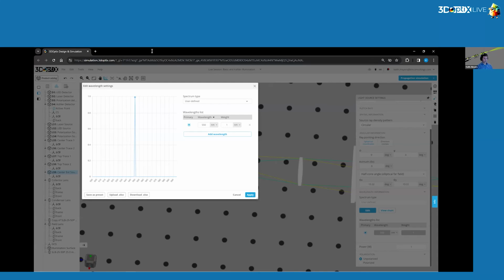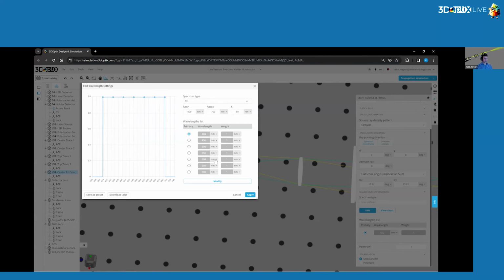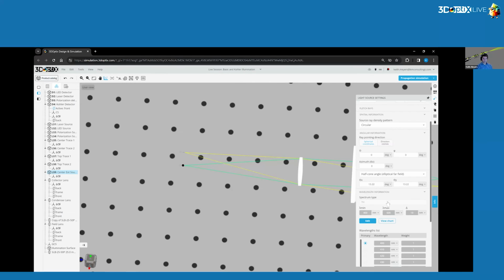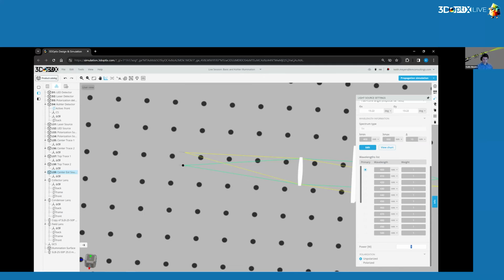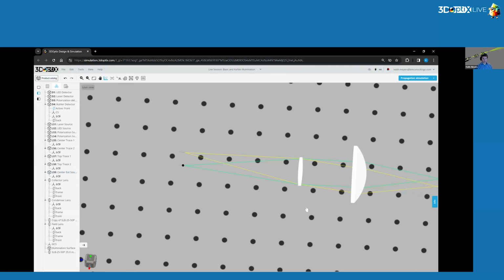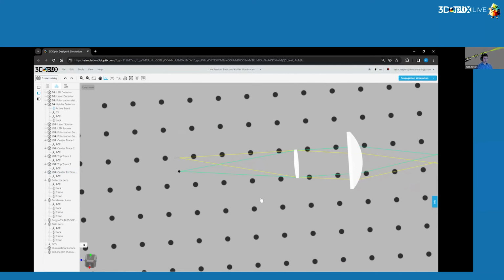Okay. And then for wavelength, we do want 400 to 600 nanometers in 10 nanometer steps. So we want to simulate a white light LED, so a broadband source. So again, top hat, just a very simple simulation of the LED. We'll go ahead and apply once the wavelengths are populated. And we'll keep the wattage a little bit lower because we're simulating source points, not the full source. We'll keep it unpolarized because it's an LED. Okay, there is the first one.